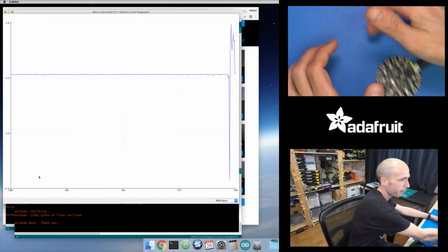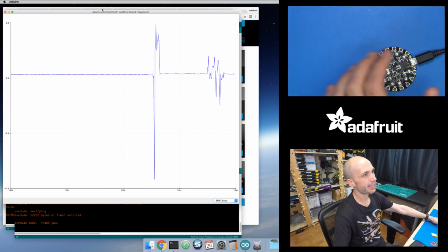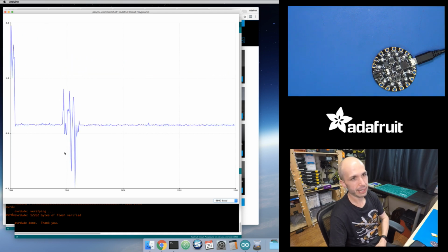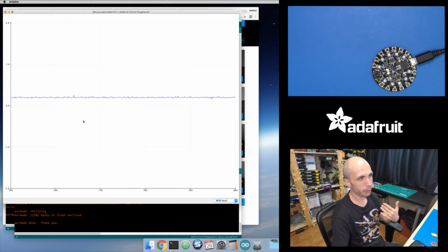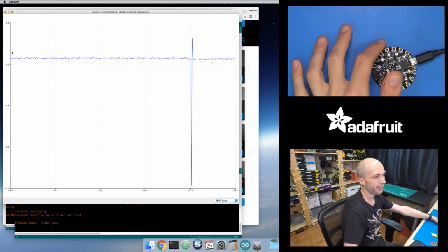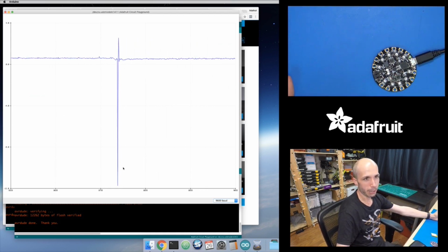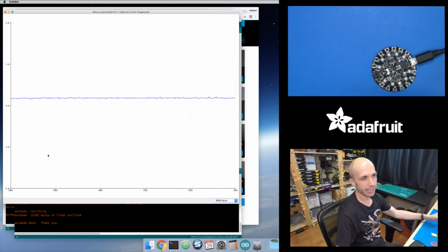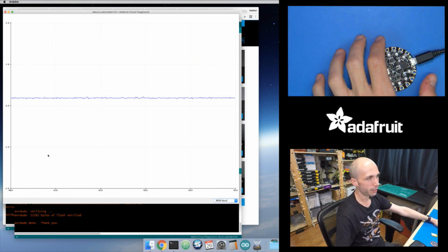And if I smack it from the other direction, I get a big spike up to about +8, or even -16 down there. So I could just put a threshold in my code that says, if I see an accelerometer value above, let's say 5, then consider that a peak. So if it's above 5 or below -5, it would capture that peak and consider it something that causes a spin.